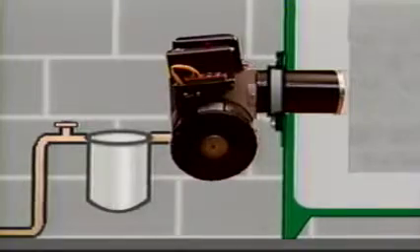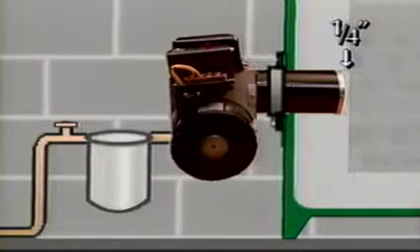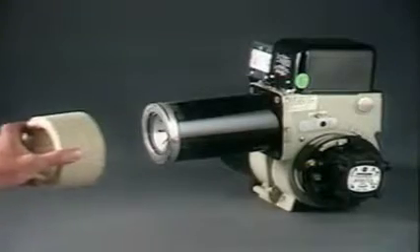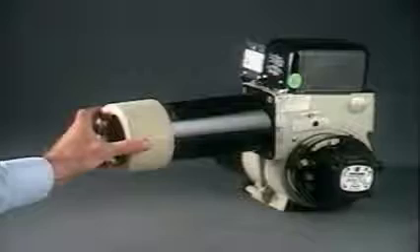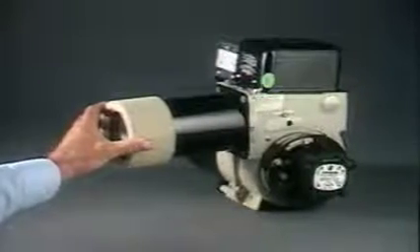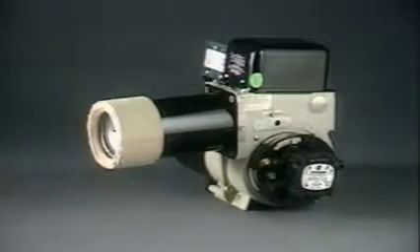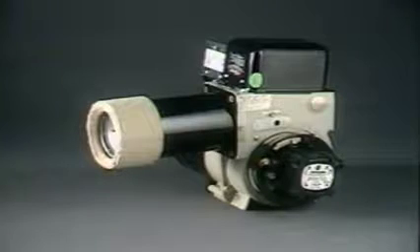The burner end cone should be positioned about 1/4 of an inch back from the inside chamber wall so that the combustion head and air tube will not become overheated by recirculating hot gases during operation. In some relatively hot applications, refractory fiber material should be placed around the outside diameter of the burner end cone and air tube to provide insulation from radiation and overheating.